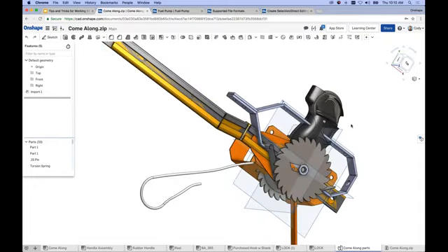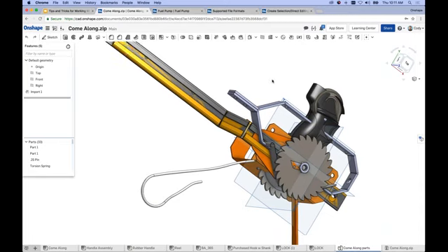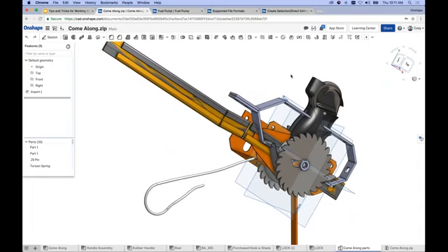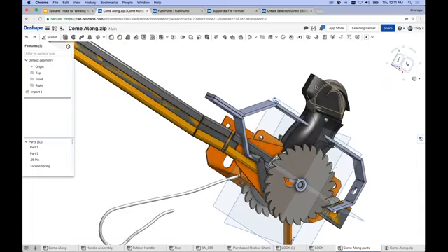Now, one big tip that I have for you is, at first this looks a little daunting, and it can, if you have larger assemblies, look kind of scary at first to say, how do I find the part that I want and make changes to it. One of the biggest tips that I can give you for working with a part studio with a number of different parts in it is the hide other parts.